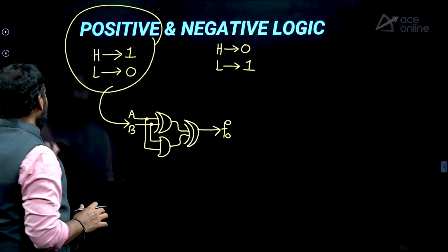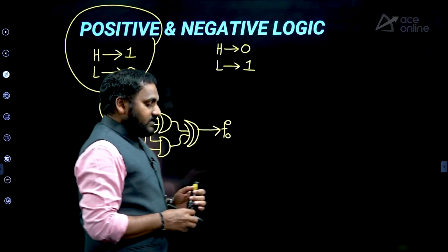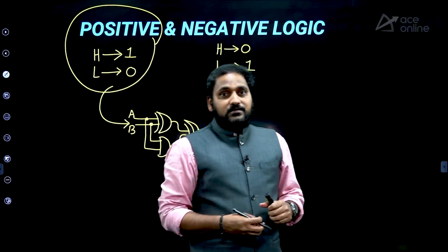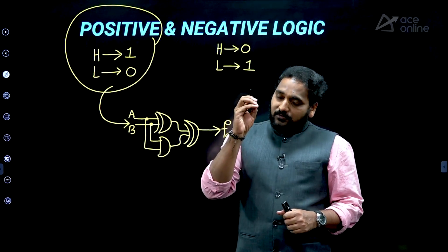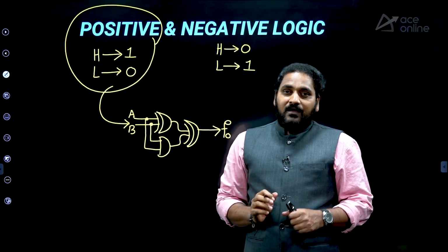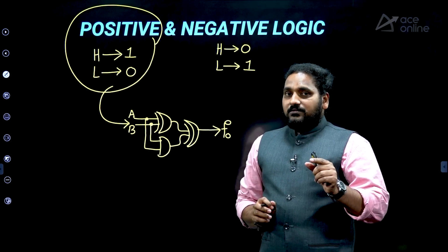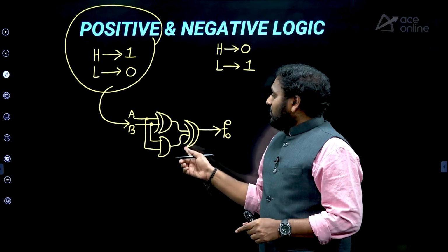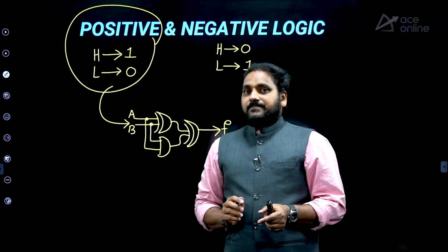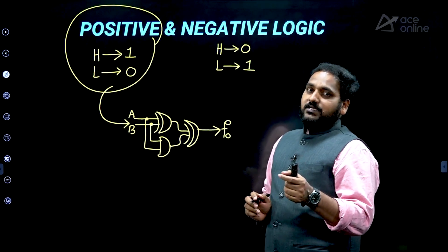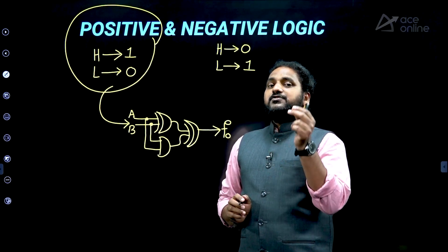Don't give a chance for unnecessary confusions. Whatever logical expressions you know and have studied, everything belongs to positive logic. Do the problem in positive logic only. After completing the solution, if required, you can convert the positive logic answer into negative logic. Do you remember the technique we discussed? We can convert positive logic into negative logic and vice versa just by applying the duality.